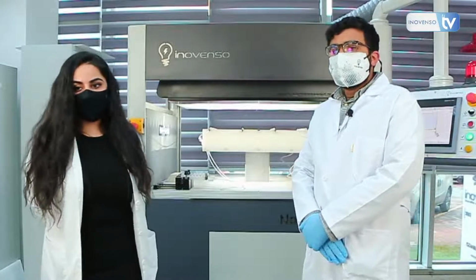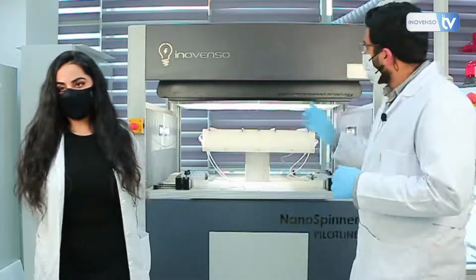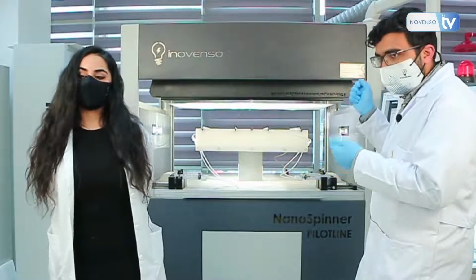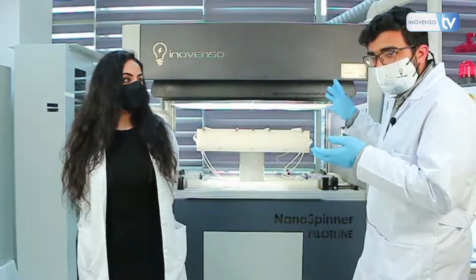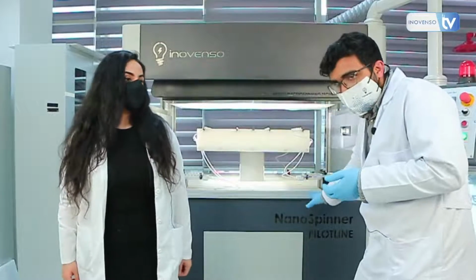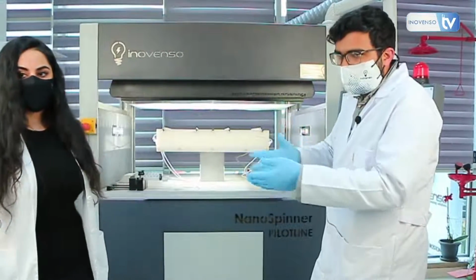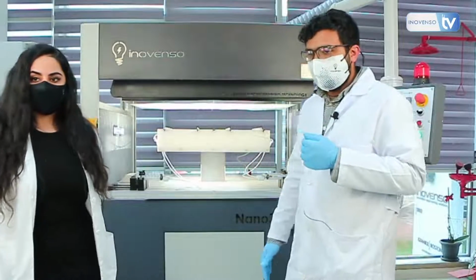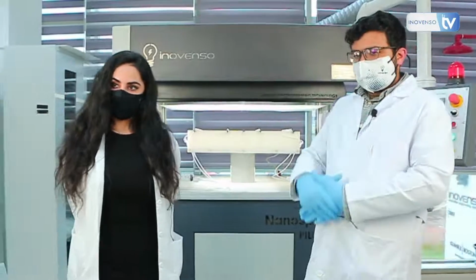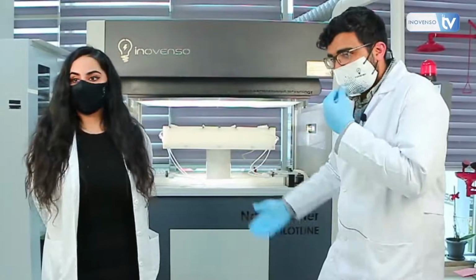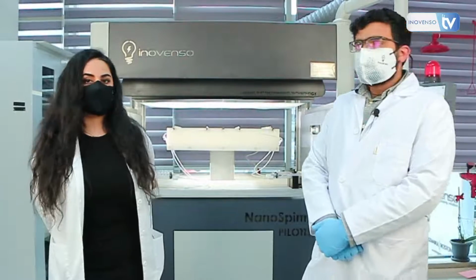Right. Another question is: how are they controlling the humidity of the system? As I mentioned before, we have a dehumidifier connection that is connected to the machine. It reduces the humidity of the chamber, as long as the chamber is closed, of course. When it's closed, you can control the relative humidity from about 20 RH up to 90 or 100 RH using the dehumidifier. Our machine basically comes with that as a particular upgrade or modification. There are, of course, additional options and modules available if you would like to add them to the system.